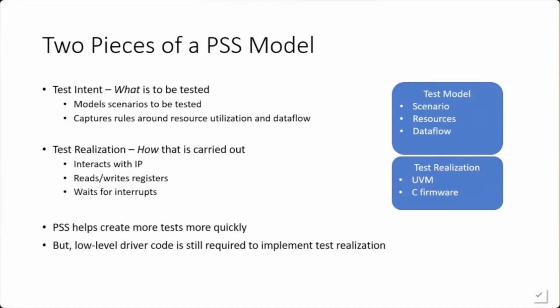What's very critical, of course, is that we have to somehow relate this high-level abstract model down to the lower-level details of how do registers get programmed in the IPs, how do we interact with interrupts, all the lower-level detail that actually makes a test go at the end of the day. So the high-level modeling details of PSS really help us describe tests much more quickly, but it's critical that we have the lower-level test realization, which is like driver software, in place to make the tests actually connect into the design.